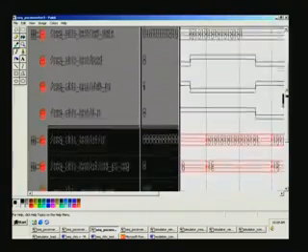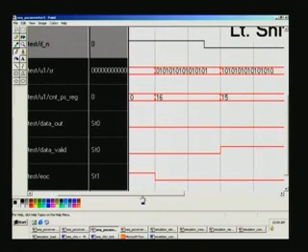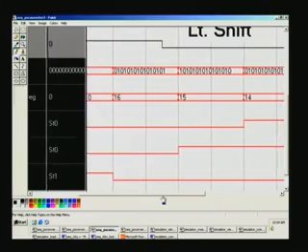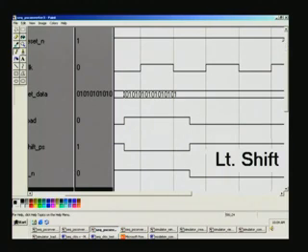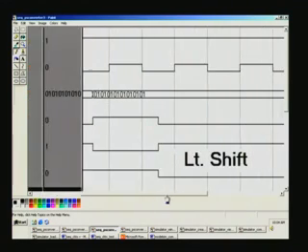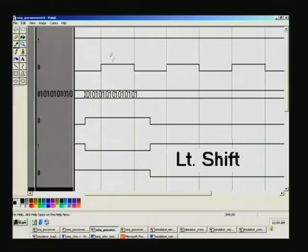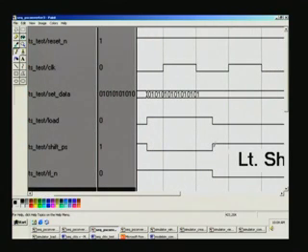Straight away we will go into the waveforms of interest, and this is once again the shift register here. Before this I will just show where the loading is. Now, this time we are not loading, this is data loaded, you can see set data, and what we load now is 0 1 0, just opposite of the previous content, and this is the load asserted, and shift starts being active right from here the moment it is loaded. So, the shift register must start with this value.